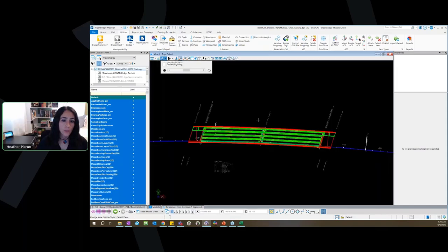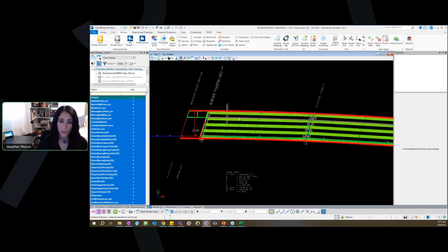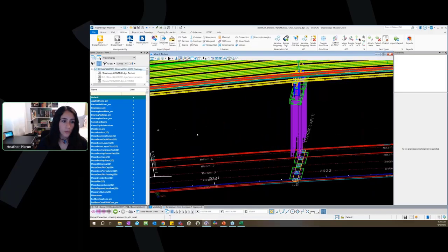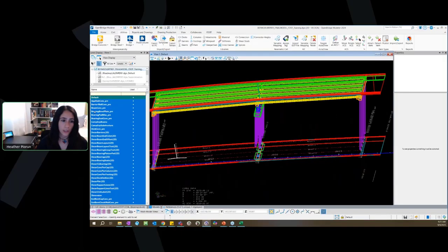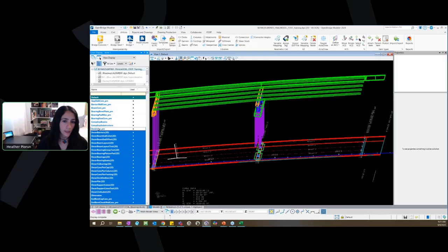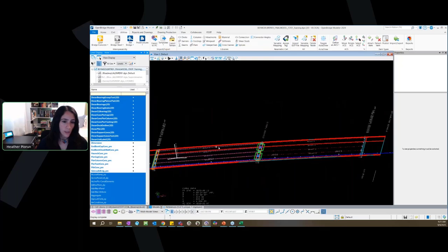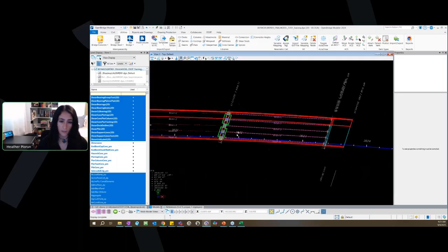So let me move this back to wireframe here, and I'm just going to delete these. So we have our wireframe view, and it is a 3D view, right? So if I don't want to look at the 3D stuff right now, I can go in and unhighlight all of the 3D, keep everything that says decor, and go back and say that I don't want any of this. So now you can see that I only have my 2D information here. So I'll go Shift, right click, T for top, and it brings me back to my unrotated view.